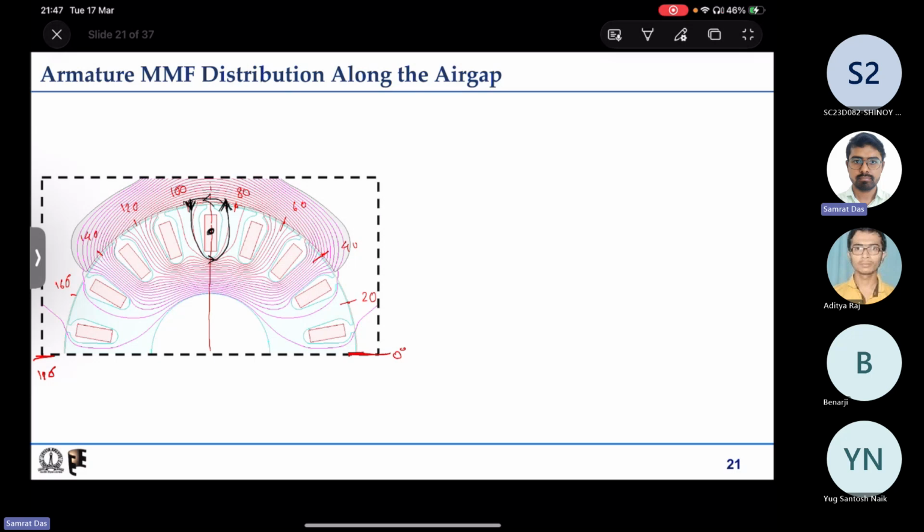Now if we construct a magnetic circuit corresponding to this, this portion indicates the reluctance of the iron, which is very low. So I am assuming it to be short. Then we have some reluctance corresponding to this small air gap, and again some reluctance corresponding to the small air gap. And of course, this is again closed through the iron, which is again short, and the flux is driven here.